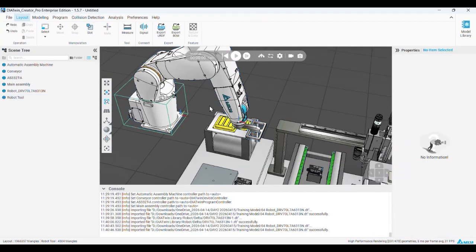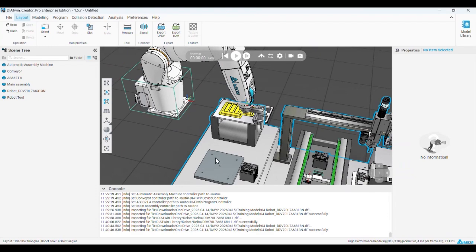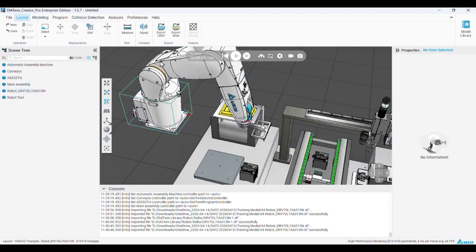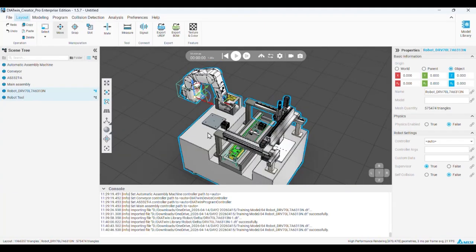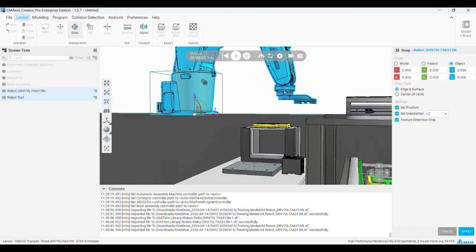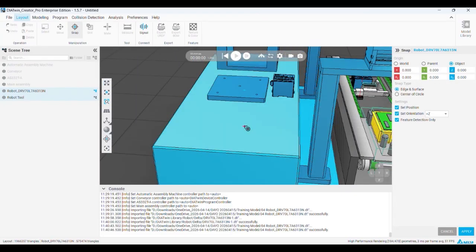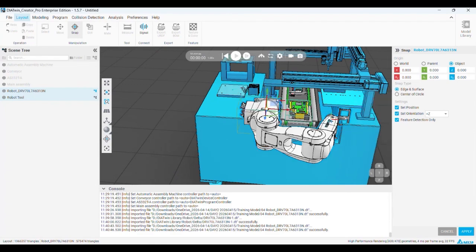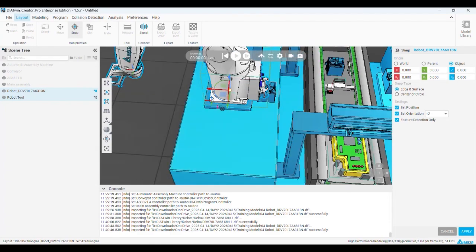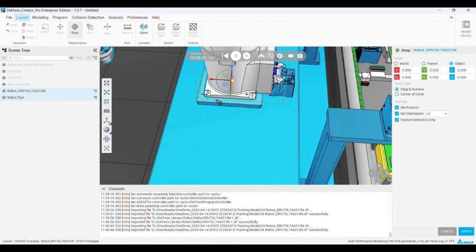And here's another thing, okay, if you want to slot the robot on this plate, now it doesn't have anything for you, right? But the easier way is like this, okay, you can just use our snap function, because actually for this kind of cases, the robot base will not move and also the frame will not move. So you can also use snap. Okay, snap means the origin of this component will snap on the feature where you select, like this. Okay, so just select the feature you press, and then I can maybe just rotate 180 degrees.